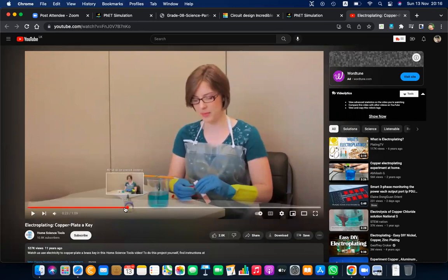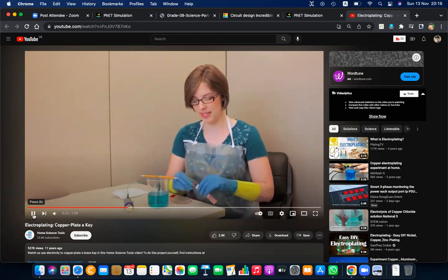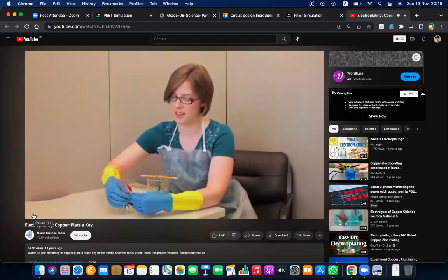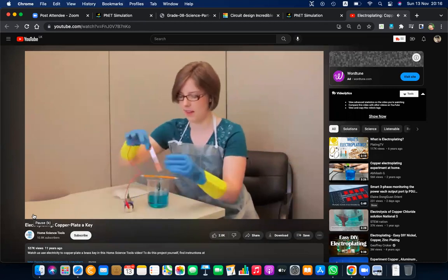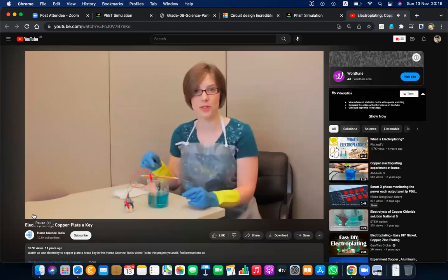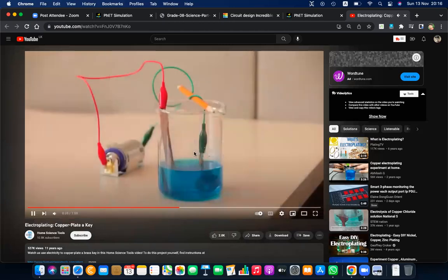The negative rod is what we are going to plate, right? Otherwise, this will happen the reverse way. So the positive end is connected to the copper strip and the negative end is connected to the metal that you're going to plate, making sure that it does not touch the key. Now, as soon as the copper strip and the key are both in the solution, an electrical circuit is formed and current is flowing. Electrolysis is now happening.